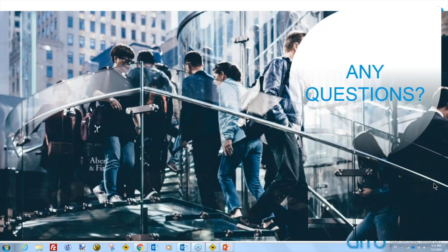Let me chime in a little bit. Based on what we observe for the application of IC, especially on large projects, when the project has started to evolve and confidence is built in the correlation between ICMV value and spot tests, the owner has made the decision to reduce the spot tests. One such example, shown during our workshop by BOMAG, is the Istanbul airport project, where more than 1,000 spot tests were required for a given day, and that was reduced to just a couple dozen tests a day, because the ICMV value can provide such coverage and measurement.